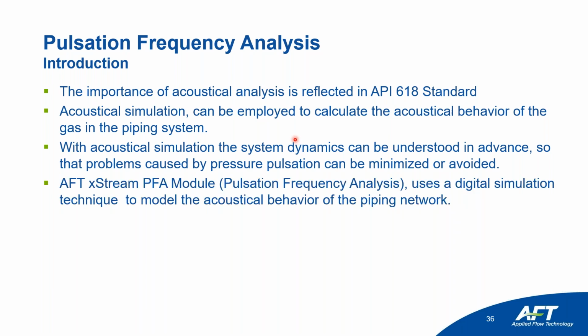AFT xStream PFA module, pulsation frequency analysis, uses a digital simulation technique to model the acoustical behavior of the piping system. What the PFA module does is it applies what we call a digital hammer, where internally it hits the pipe and sees what acoustical natural frequencies are excited.